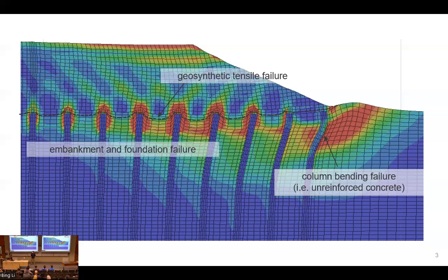But if you can do it in 2D, that can save you a lot of time because 2D analysis is easier to put together. It's faster to run. If you want to do 3D, that's when you know you have to fight the 3D. Sometimes the consideration may stem from the budget. If you're going to be spending so much time on 3D analysis, your project has to have the budget to support it.